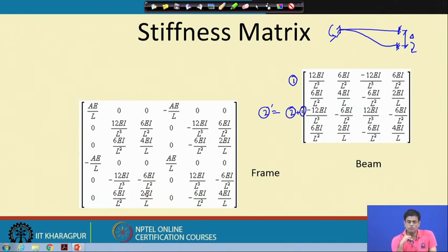So, as a whole, the idea of why we need to know the rank of a matrix here for structural analysis is that if there is a rank deficiency, we cannot invert the matrix.